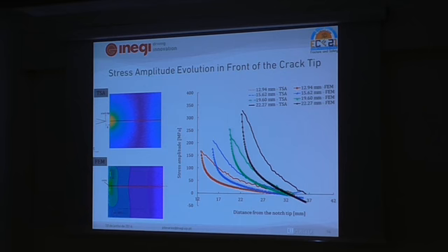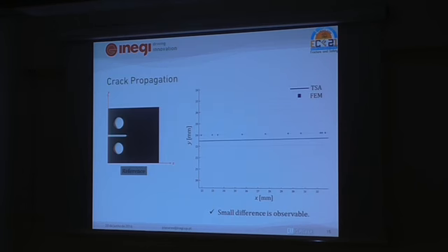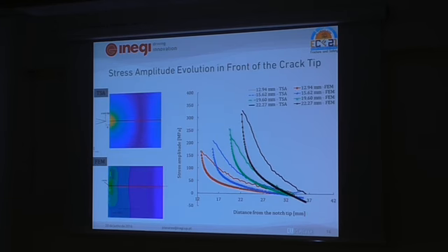Well, additional information to this would be that the loading is dynamic, of course. We preserve adiabatic conditions by loading at least 4 times above the fatigue frequency, the testing frequency. So we were testing at 10 hertz and acquiring at 40 or 50 hertz, I think. Not entirely sure.